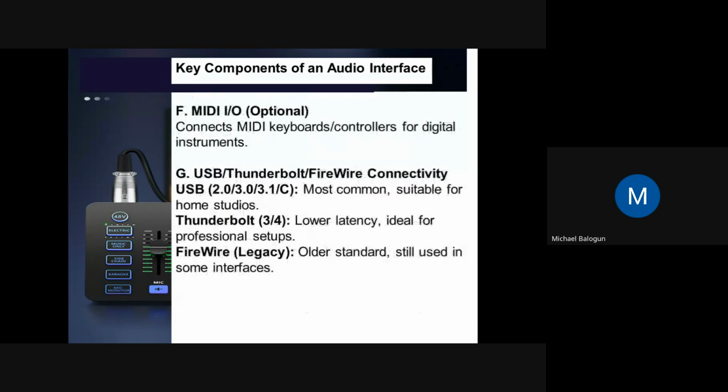What's the implication of putting phantom power on a dynamic mic? Well, it can damage it because you're supplying a voltage that it doesn't need. However, 48 volts is negligible, but over a long time, if you leave it there permanently, it could. Within a short time, does it make any noise? Sometimes it introduces noise, sometimes it doesn't, depending on the quality of the microphone.